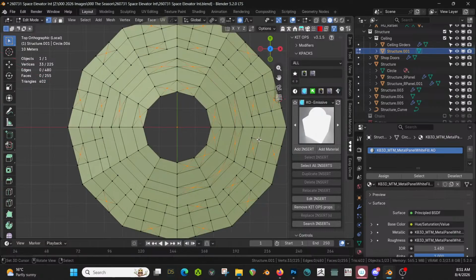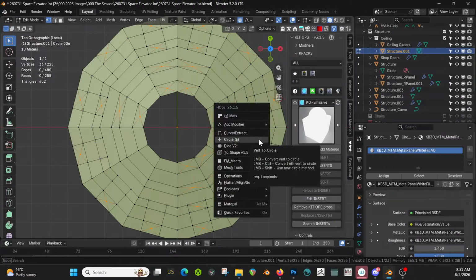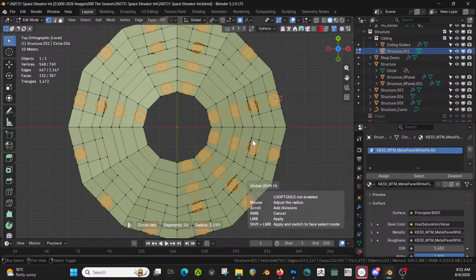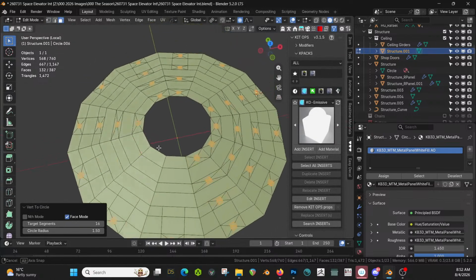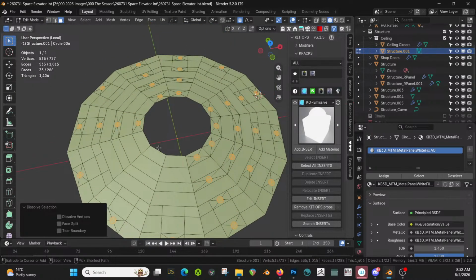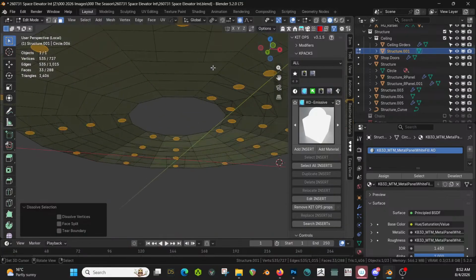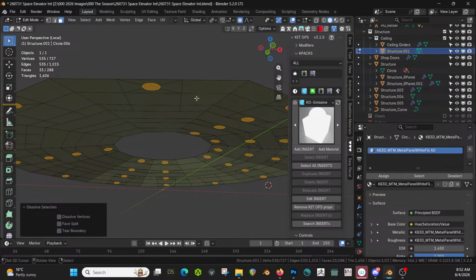Okay, so that's just the center faces. Cool, cool, cool. Circle. Make them a bit smaller. They all line up. They're all the same size. Cool. 3, Control X. There we go. Now, Alt-E along normals. We could go up.